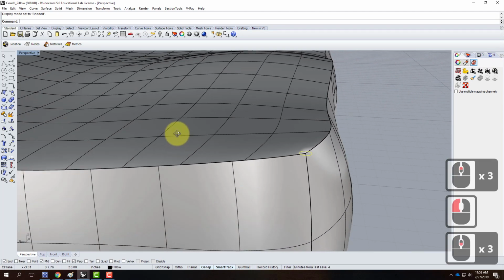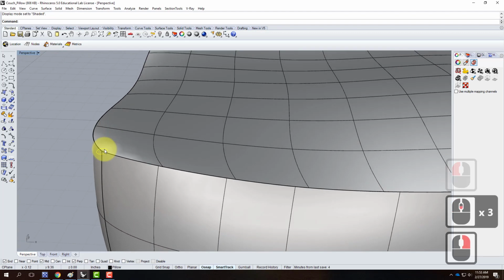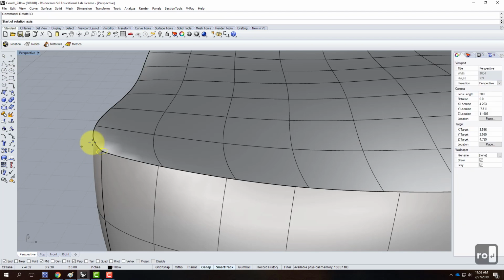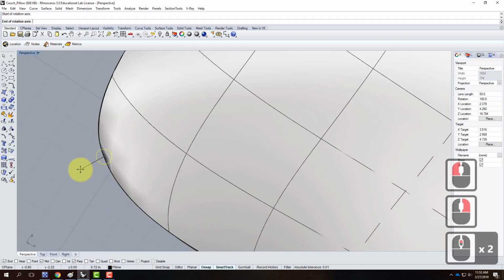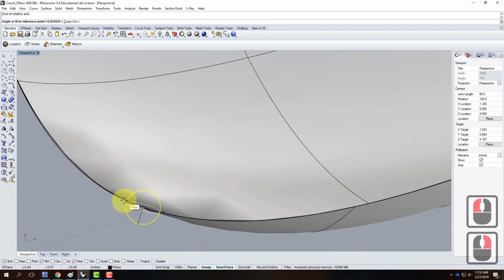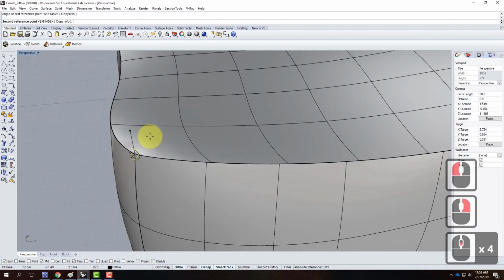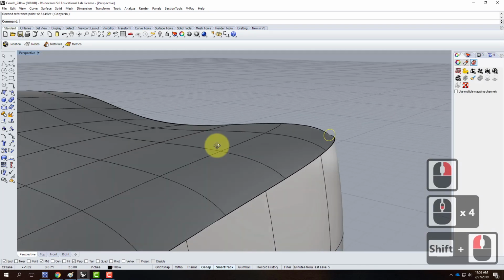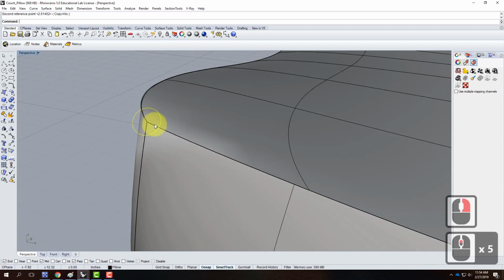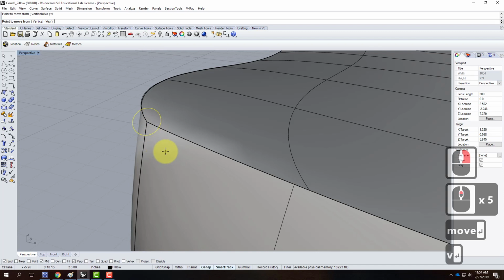Now I need to stand that little circle up so that it's roughly at 45 degrees. So I'm going to use a rotate 3D. We'll start. And I'm going to snap. And we'll say right about there. And I'll snap to right about there at perpendicular. I'll hold down Shift so that that stands up. You see how that's kind of standing up roughly at 45 degrees there? Next thing to do would be to move. I'm going to move it vertically just a little bit.